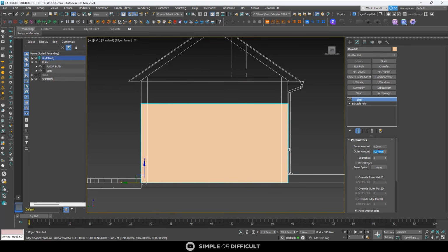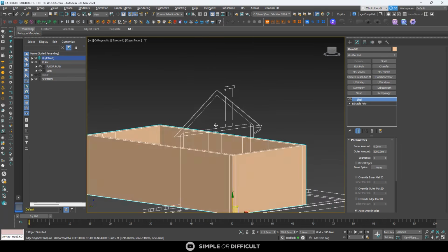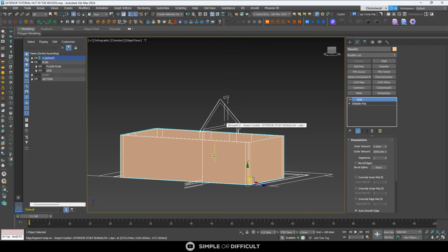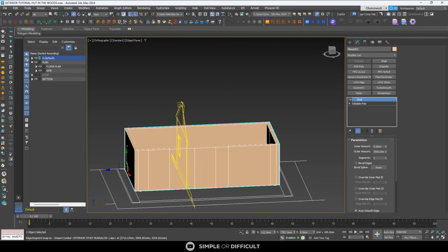In fact, let's see what 3 meters looks like. Okay, 3 meters is fine. Because this building is a gable roofed building and we need to do some things over here. In my experience, modeling it like this and then doing another part that will go all the way to the roof is the best way, because to create openings and also get this gable easily, this is the best way I know to do it, right? So let's just go ahead and do this.